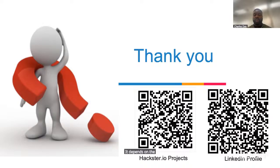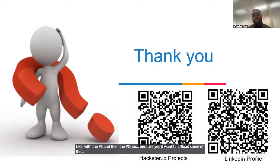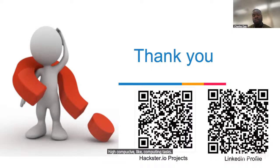Most of them can accelerate AI tasks, but it depends on the kind of project you want to do, or the chip itself. First, I would say it should have some advanced PS and PL, because you'd want to offload some of the high computing tasks from the PS to the PL.